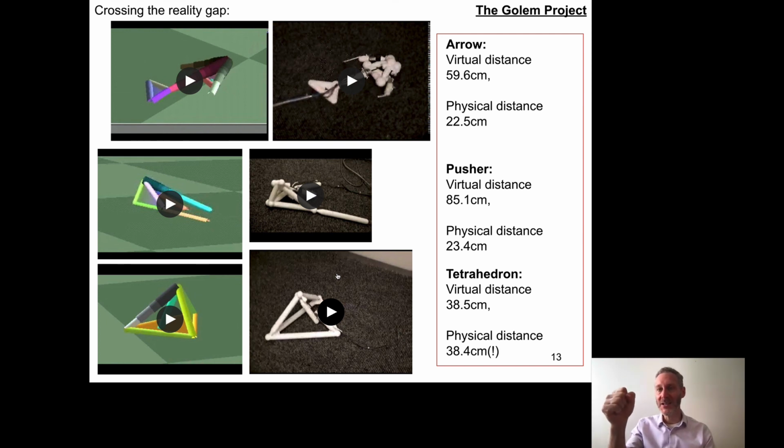If your stance foot pushes horizontally behind you when you're on ice, your foot is likely to slip out from under you and you're likely to fall. So you make yourself less affected by the surface property you're moving over if you take more vertical steps. You move more slowly because you're moving more vertically than horizontally. But you sort of decouple your dynamics.